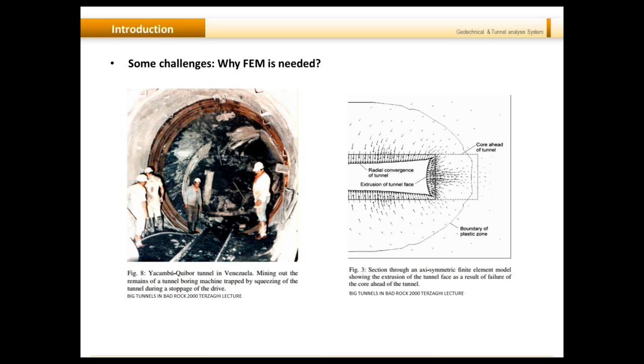It is absolutely critical. So you need finite element analysis to extract these forces occurring on the face, and then apply the jack forces or the face pressure forces accordingly in your numerical model. So therefore, for ground squeezing, you need accurate estimation of face pressure.